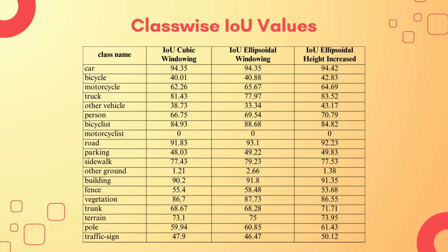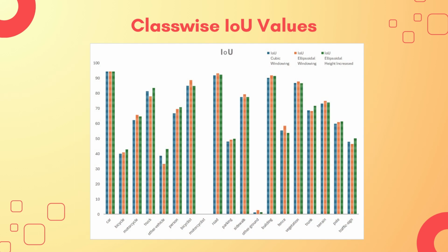We analyzed the object class-wise mIoU values during the initial development and after each major development and integration phase. Here, we used 19 class objects from the SemanticKITTI dataset, which is derived from the KITTI Vision odometry benchmark. This dataset provides dense point-wise annotations for the complete 360-degree field of view of automotive LiDAR, enabling comprehensive analysis and accurate segmentation of various object classes.